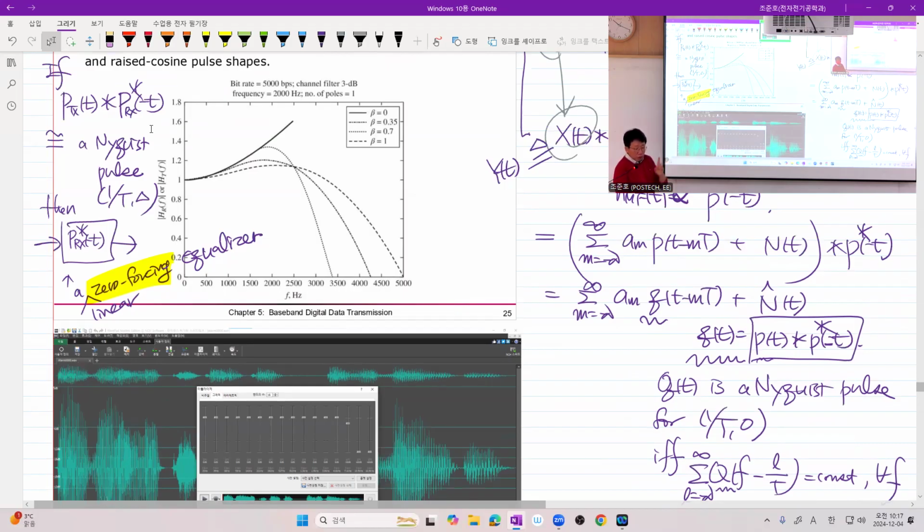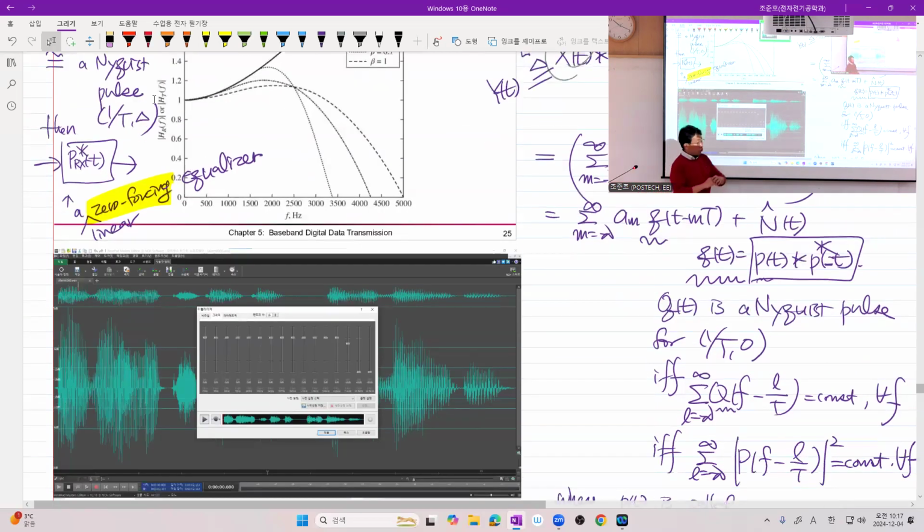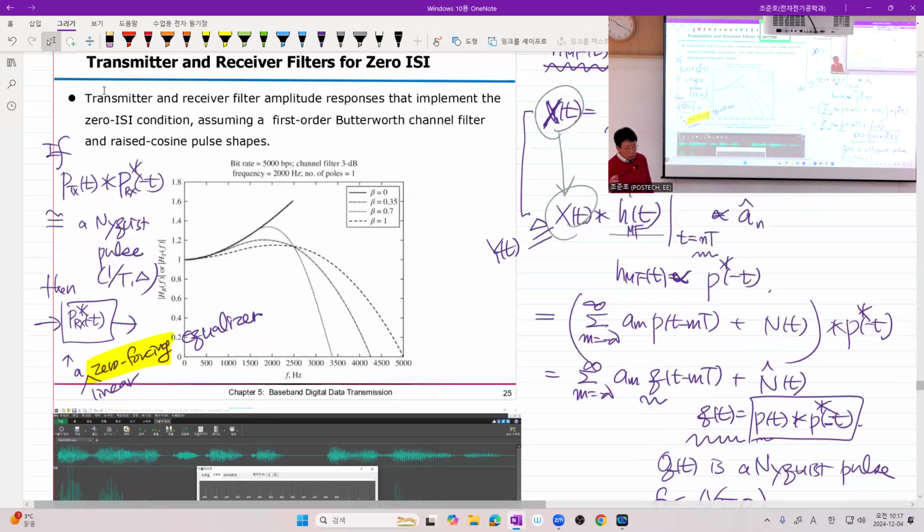Because in many cases, for this audio equalizer, you don't care about sampling rate and sampling offset. However, when you talk about zero forcing or sometimes MMSE or some other criteria that exist, you talk about equalizers, your definition or optimality of the equalizer is related to Nyquist's criterion on zero intersymbol interference. Nyquist's definition of the absence of intersymbol interference. So be careful.